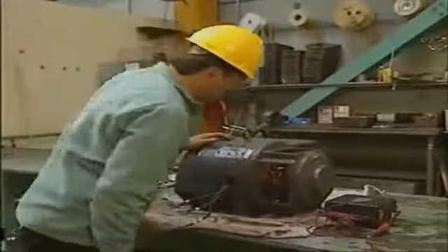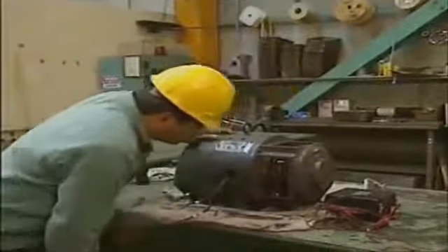First, it should be checked carefully for any obvious problems, such as broken wires, loose screws, short brushes, and charred insulation. The brushes and the brush rigging should also be checked. The armature and field windings are also checked. It's common practice to look for grounds, opens, and shorts. These are the problems that occur frequently in all types of electric motors and can prevent them from operating.